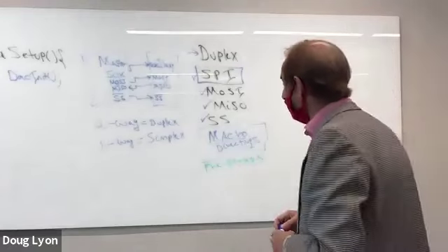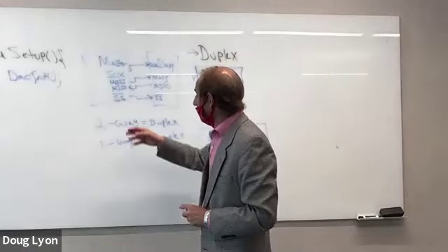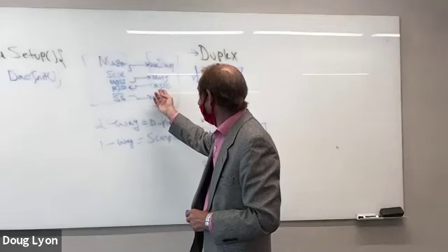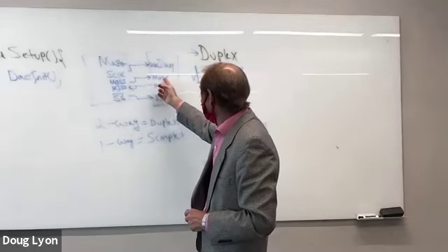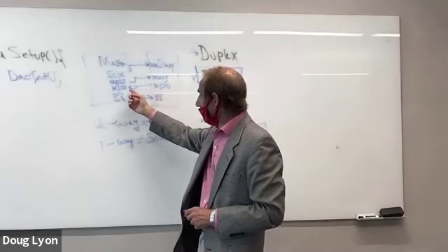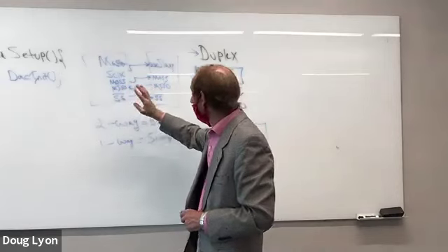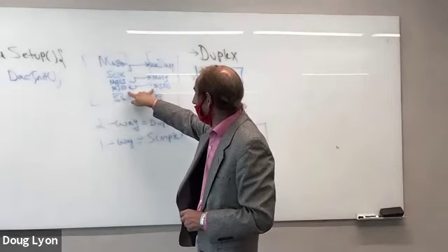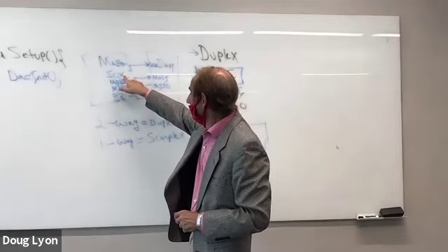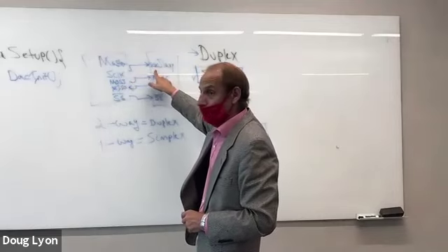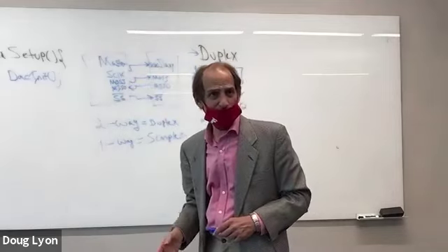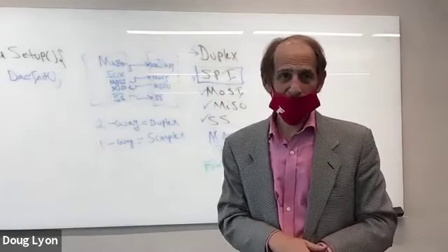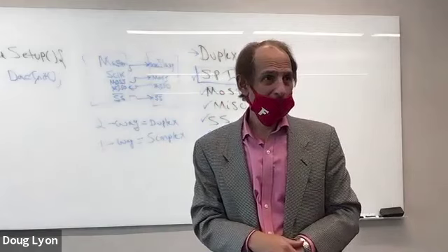How come it's duplex? Because I have a master in from the slave out. So I can communicate to the slave, and at the same exact time, it can acknowledge. Moreover, when it does its acknowledgement, the bit framing will be dictated by the serial clock that comes from the master. What does that mean, bit framing? I don't understand. Can somebody please explain the term bit framing?